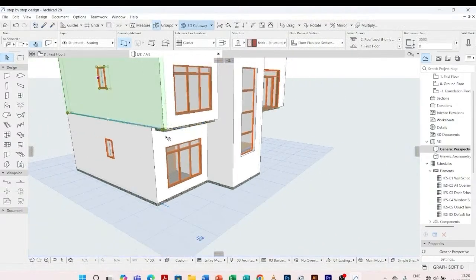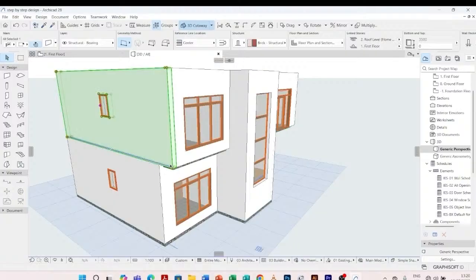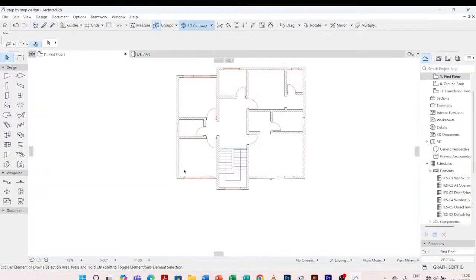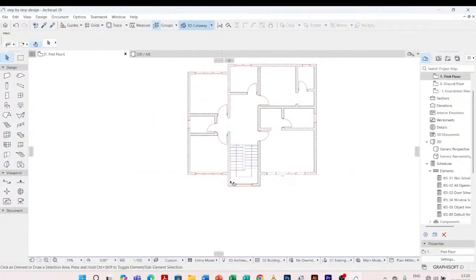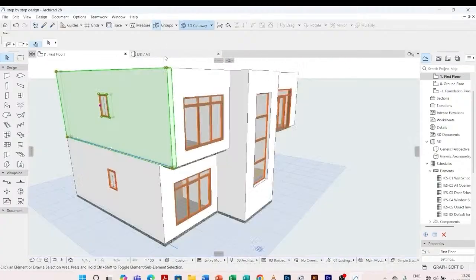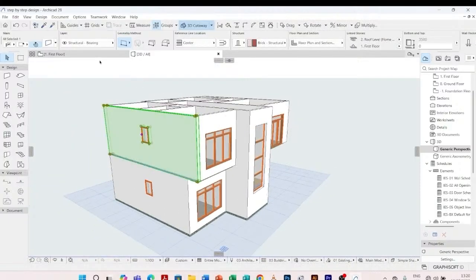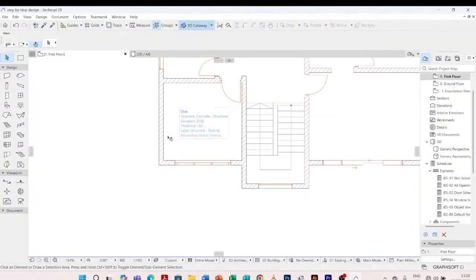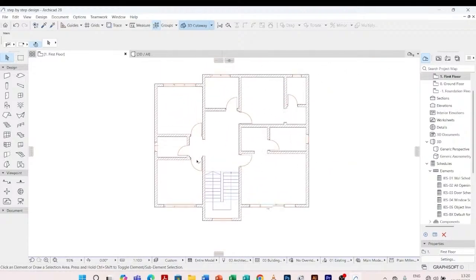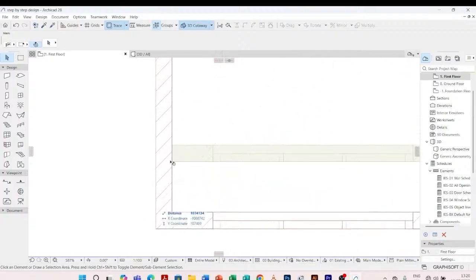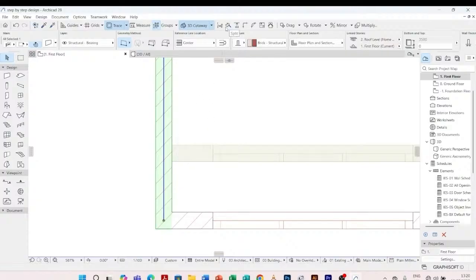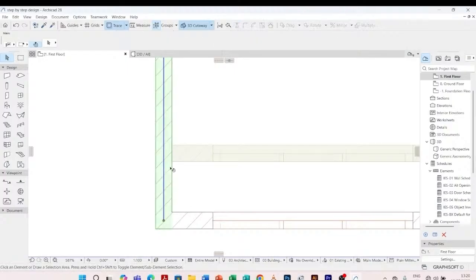That means I'll have to cut this wall, so that I only move this wall down. I can cut it from the first floor. Let me see where it is exactly. First floor. I need to see what is down. I press Alt F2. That is to trace my ground floor, so that I know where exactly I'm going to cut this from. I click on my wall, I split or I adjust. For this case, I want to split this wall.